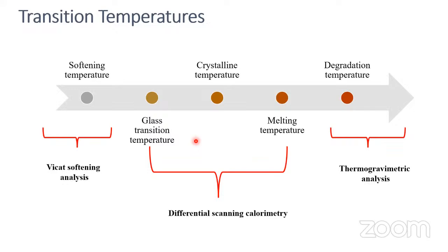That temperature we can call the glass transition temperature. And again, if you move forward by providing some more temperature to your polymeric material, then obviously after that rubbery behavior, your material will move to melt, to become a molten form.